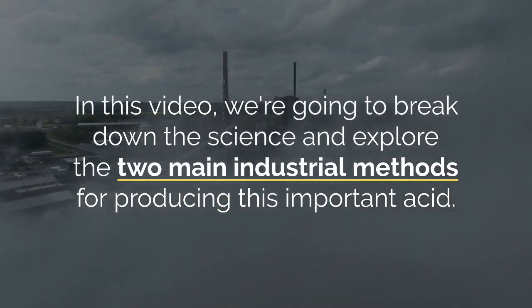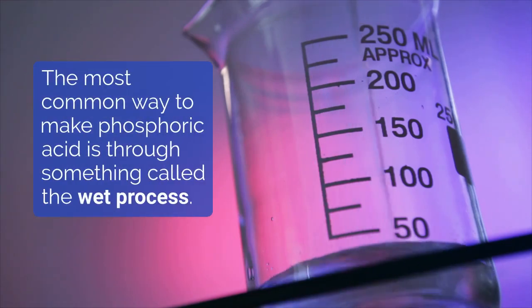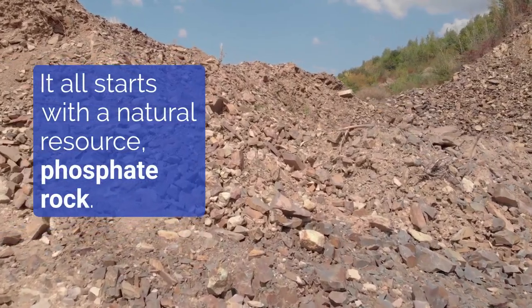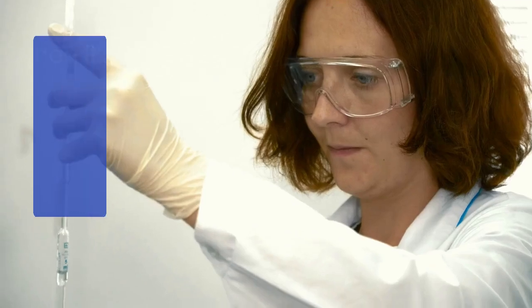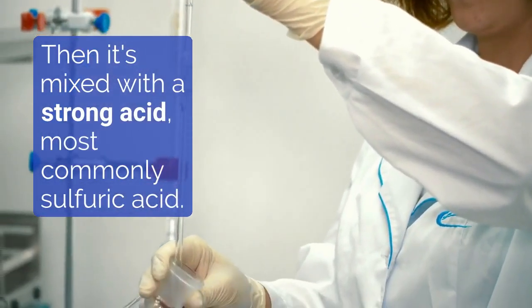important acid. The most common way to make phosphoric acid is through something called the wet process. This method is responsible for the vast majority of phosphoric acid produced globally, primarily for use in fertilizers. It all starts with a natural resource, phosphate rock. This rock is essentially calcium phosphate, mined from the earth. The first step is to crush this rock into a fine powder. Then, it's mixed with a strong acid, most commonly sulfuric acid.